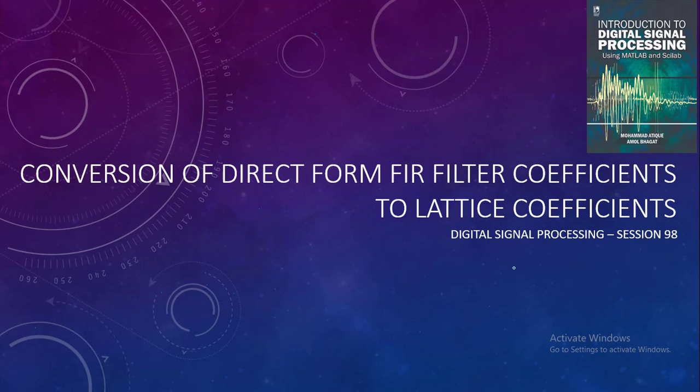In previous session, we have seen lattice structure for realization of FIR systems or FIR filters. We also seen how to obtain the direct form filter coefficients from the lattice structure coefficients. In today's session, we will discuss how to obtain the lattice coefficients from the direct form FIR filter coefficient. Okay, so we will try to identify the values of ki's from the alphas.